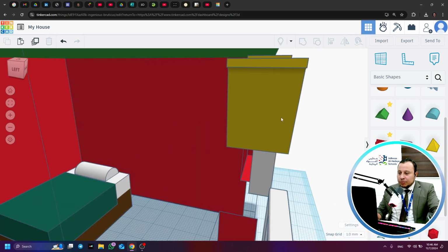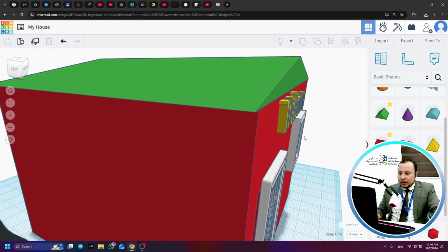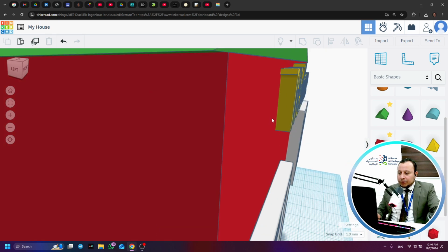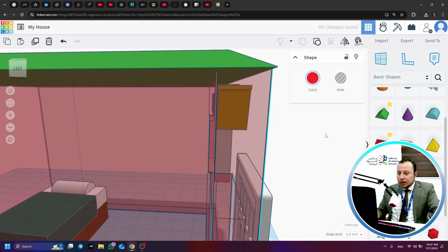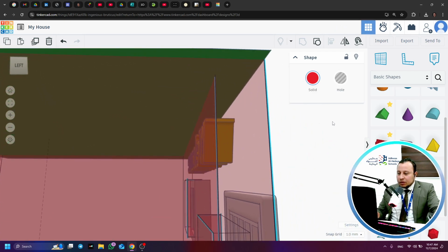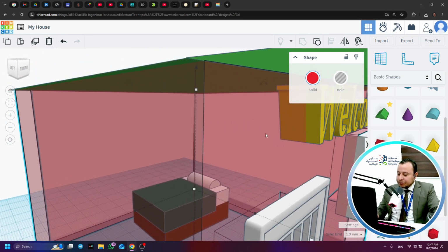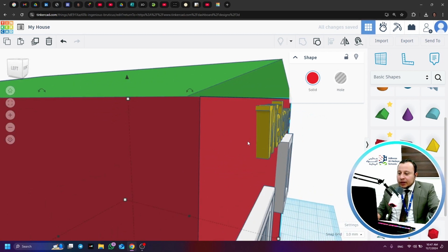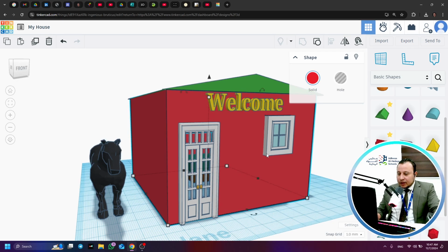You see it's penetrating through the wall, and I guess if we zoom in too much, you will be able to see that part of it, or let's click T. Now part of it is already behind the wall, or just stuck, and will be printed with the wall in a way. So that's how you make sure it's not going to fall down after printing.